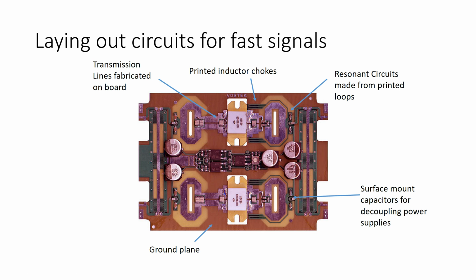In this course we've used old-fashioned radial wire lead components so that we could plug them into our breadboard. At high frequencies these would be radiators and couple horribly to other leads via stray capacitance. So one wants very small capacitors soldered directly onto the board, and most components these days are surface mount. So all the power supplies come in with a surface mount capacitor to ground. Finally, this board here, you see the dark part all around here, is actually a ground plane, and so this is a region at zero potential, and it just helps to minimize capacitance and inductance on the board.